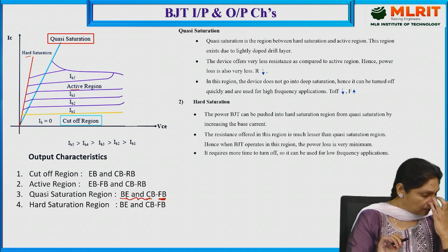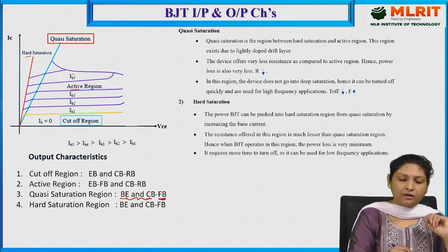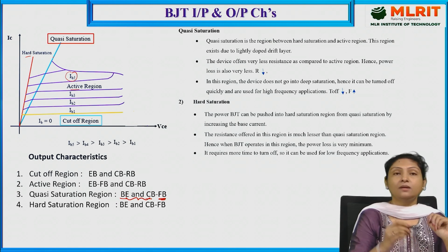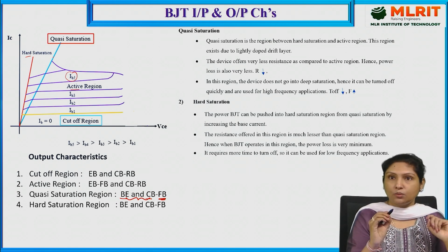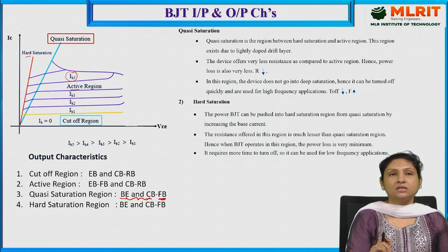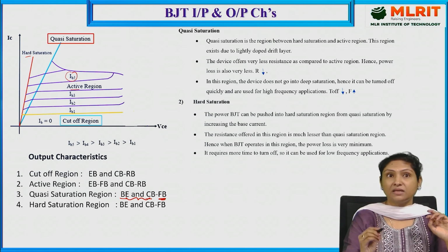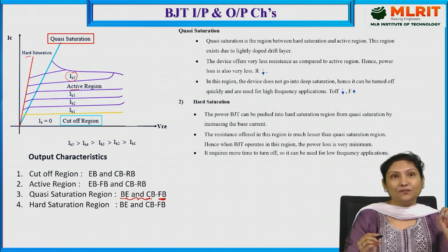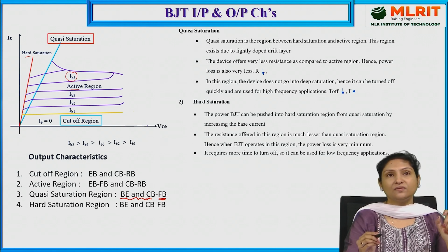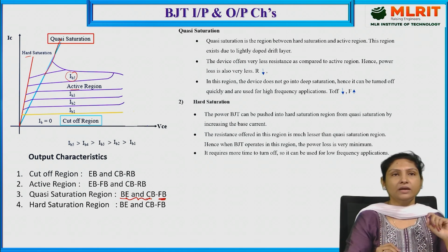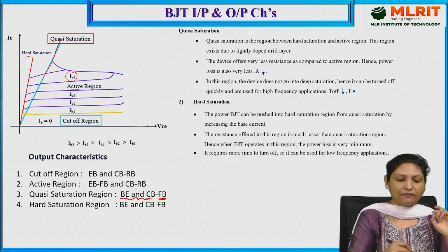And if we increase the current beyond IB5, because of the N- layer which we have actually seen in the structure, the additional layer so-called N- region, which is nothing but the drift region I said, the current will be increased further in an aggressive way after IB5.